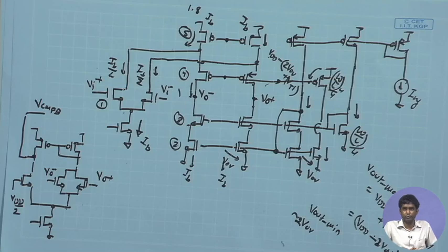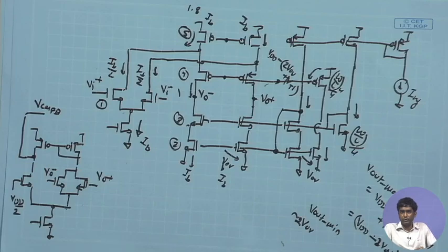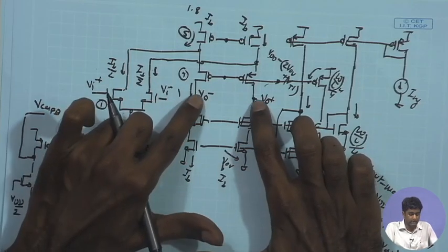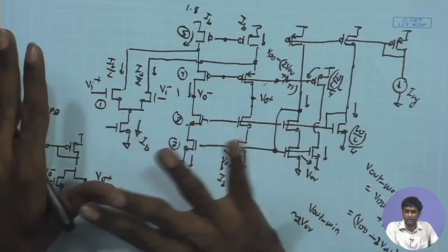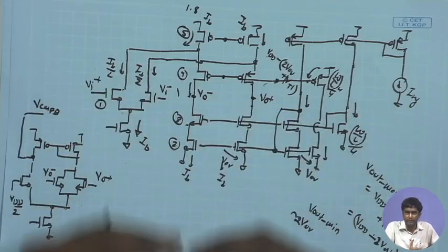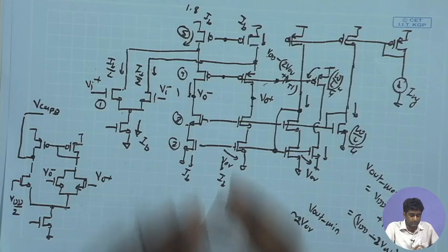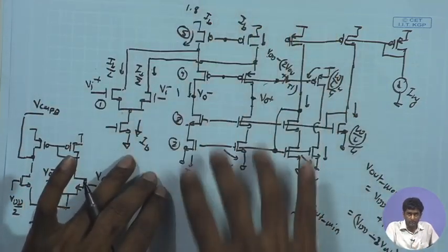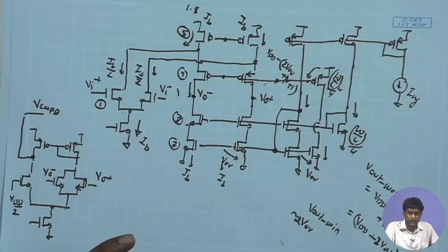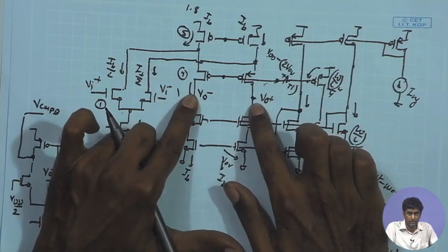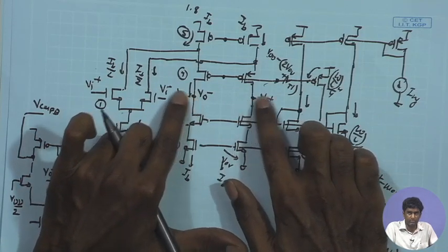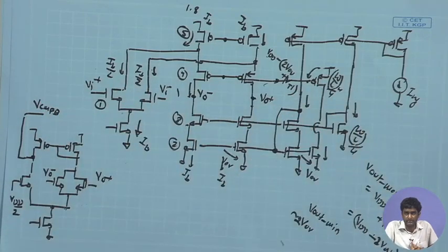And remember, the input DC bias point is once again something we can obtain using large resistive feedback from the output to the input. So, we are not worrying about the input DC bias point, and the advantage of the folded cascode is that having the output DC point determining the input DC point does not affect the output swing. We saw that in the unfolded case, the normal stacked cascode amplifier differential version, there of course the output DC potential cannot be directly connected to the input DC potential because it affects the output swing negatively.